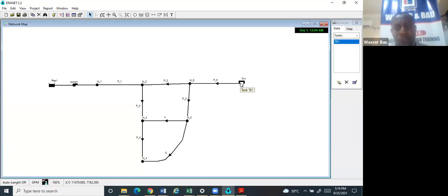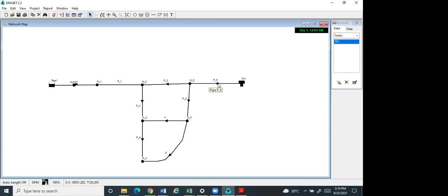While we are working on the other one, can you make sure that you have 2 parameters in the node and 2 parameters in the pump? And if it doesn't run, is it giving you 2 reports, or only 1? It's giving me 2 reports. What is the second one? The second report is: 1 or more errors in input file. Yeah, the same thing it's giving me also.